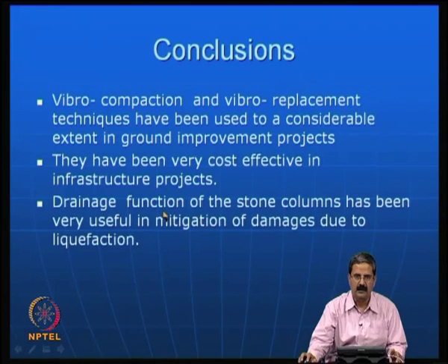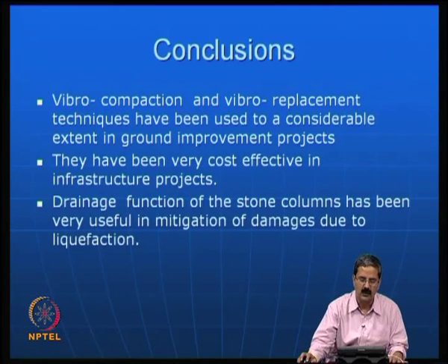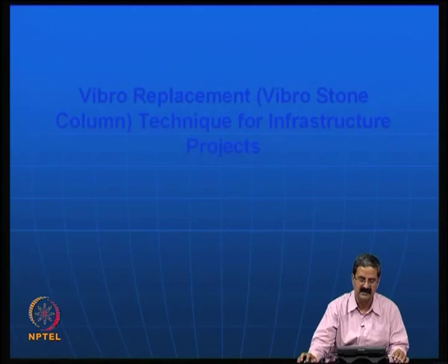Particularly in earthquake conditions, the dissipation of pore pressure is very important, so you need to design for the magnitude of the earthquake, the number of cycles of that earthquake, and its pore pressure dissipation. People have to do a rigorous job in some of these things.